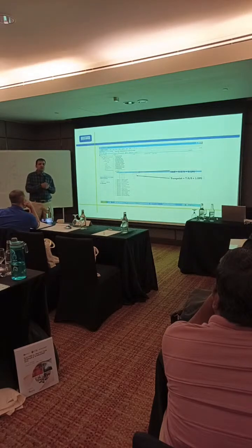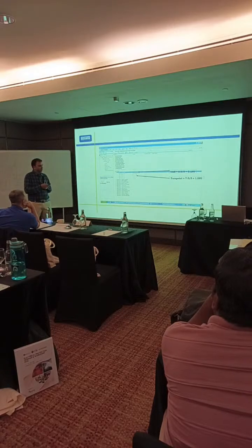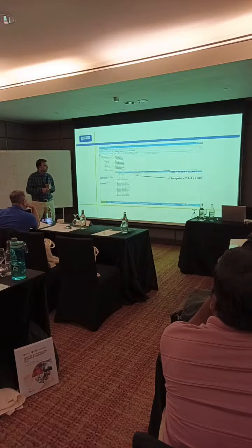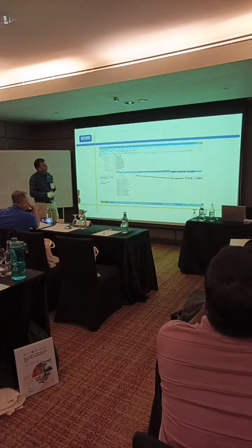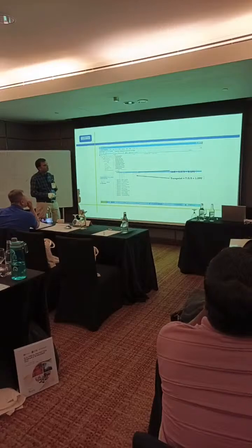Yes, because there are different voltage levels, different current ratings. So from the per unit we can calculate for each winding. While in generator both are the same, so that is why it is written in current. So we can convert this also in PU. As you can see, the rating is 5 ampere, so we divided it by 5. Then the setting is 0.1 PU. Turn point is 7.5 ampere, so we divided it by 5, so it is 1.5.